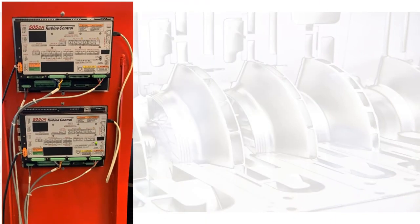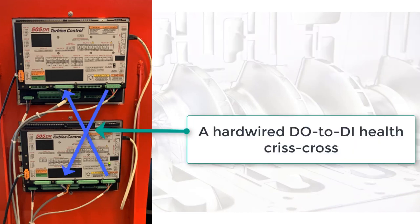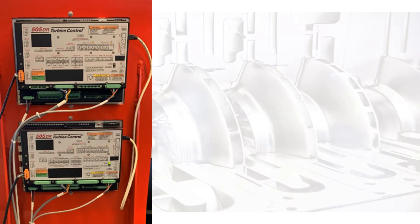The syscon and backup units communicate to each other via a direct connect Ethernet link. This link provides the data path for the syscon to keep the backup unit in sync. The units also communicate to each other via a hardwired DO to DI health crisscross link. This provides the mechanism for transferring control.